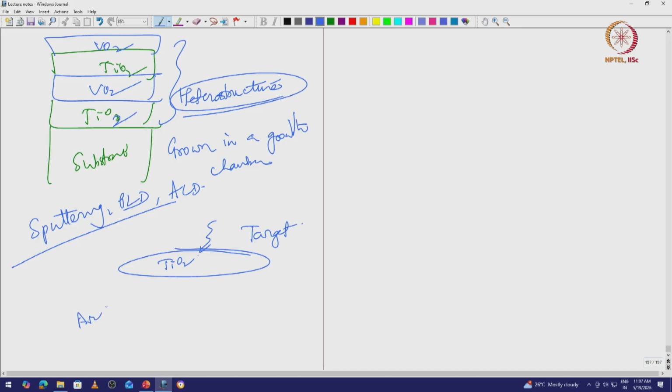So this argon atmosphere near the magnetron gets ionized. There is something called a magnetron, right. So when I apply some kind of a bias to the magnetron, the argon ions ionize, and these argon ions go and hit your target, right. So this is like a missile, or a projectile, going and hitting the target, and so the target gives away a lot of debris,